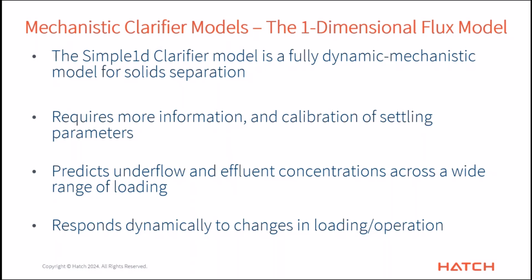Now it does require more information to use this. You need to specify a lot of the physical details: what is the surface area, what is the depth, and you also need to calibrate the settling parameters. I'm going to talk about that a little bit down the road. But basically, it predicts underflow and overflow concentrations, in fact a concentration for all 10 layers in your model. And it is also a fully dynamic model, which means it responds dynamically to changes in loading and operation.